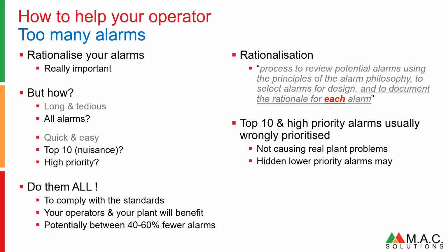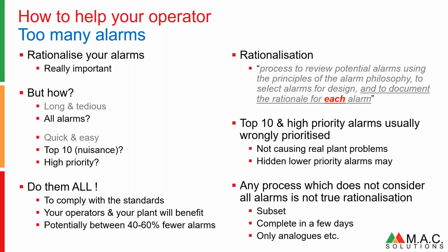So think about that. Dealing with rationalizing all your alarms. Any process that doesn't consider all the alarms is not true rationalization. If you do a subset, you've not rationalized your alarms properly. You've not done anything. If anyone comes to you and tells you that they can complete this process and rationalize your alarms in a couple of days, use our piece of software, we'll do this for you, sadly, they're snake oil salesmen. They're not telling you the truth. They are not rationalizing your alarms.